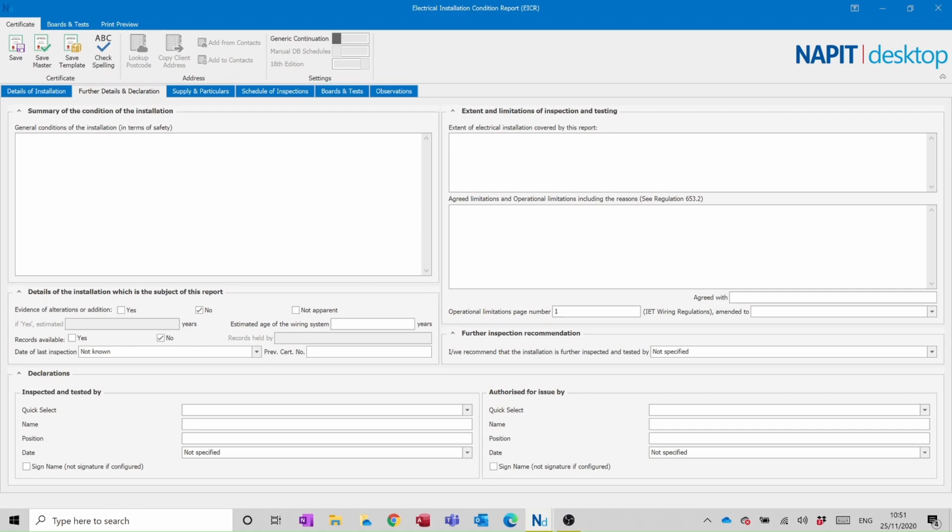I know Guidance Note 3 does suggest that we can exclude the testing of fire alarm and emergency light systems beyond the point of utilisation, but it doesn't hurt to put that in there as well, because there's other elements of BS 7671 which kind of suggest you should be doing that. So if you're making clear what you are and aren't doing, that's a good thing.